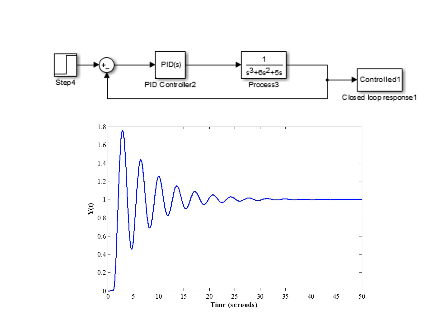So this is how it works. See, it's a transfer function. Here we have used Ziegler-Nichols aiming for a 25% offset. So we can check that. Here this is the input. So 1, 2, so it is more than this. So it is more. So it is not maintaining the 25% offset. So we have to reduce the value. We have to tune the parameters and go for it. Okay. So this is how we have to do it in MATLAB.